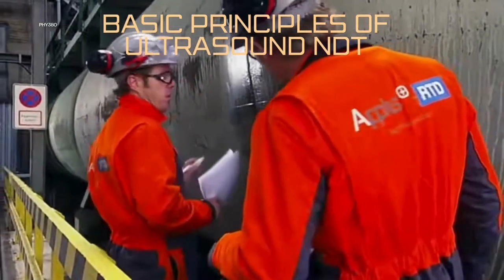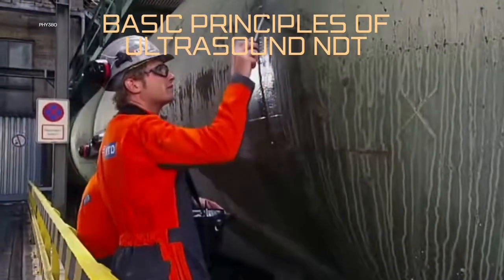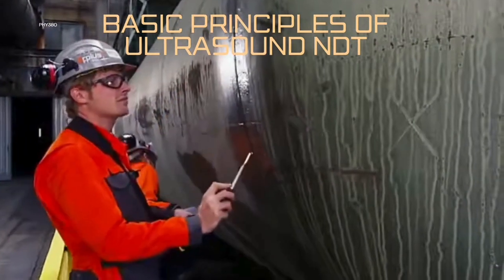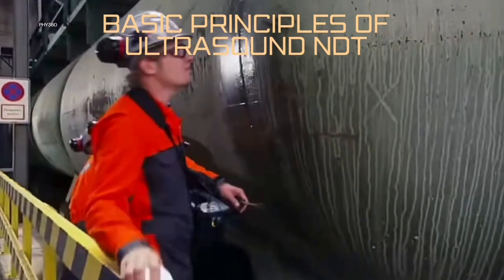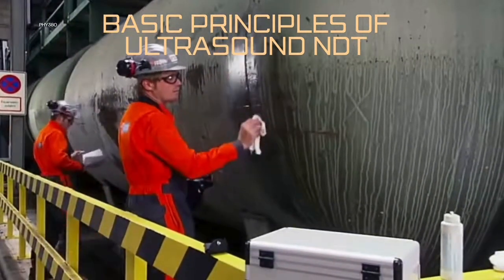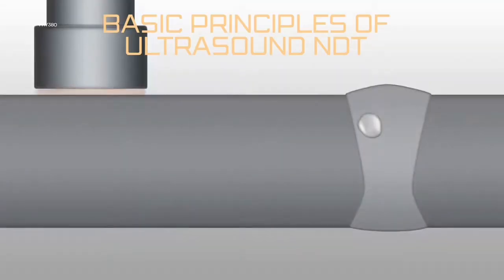It is possible to investigate whether there are discontinuities under the surface using ultrasonic sound waves. Ultrasound has such a high frequency that people cannot hear it. The vibrations can, however, be measured with sensitive measuring equipment. Using this storage vessel, a weld is checked for internal discontinuities. First, the object being examined must be cleaned and free of any material that may interfere with the exam.